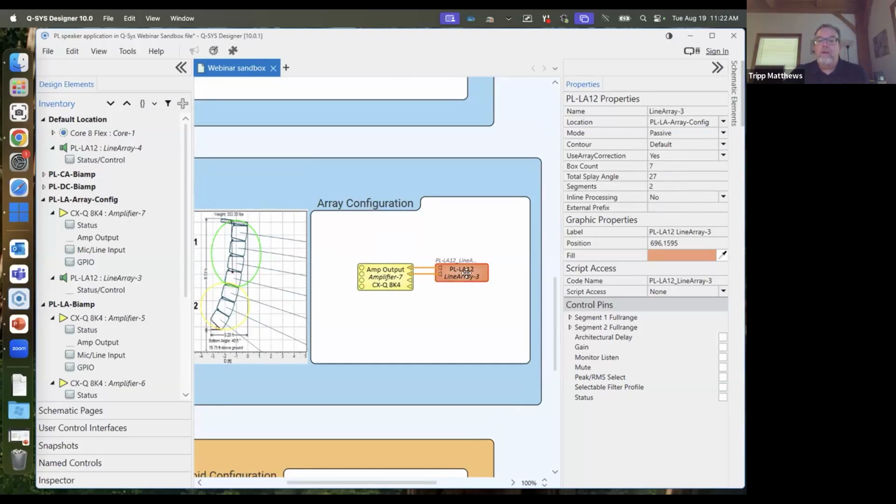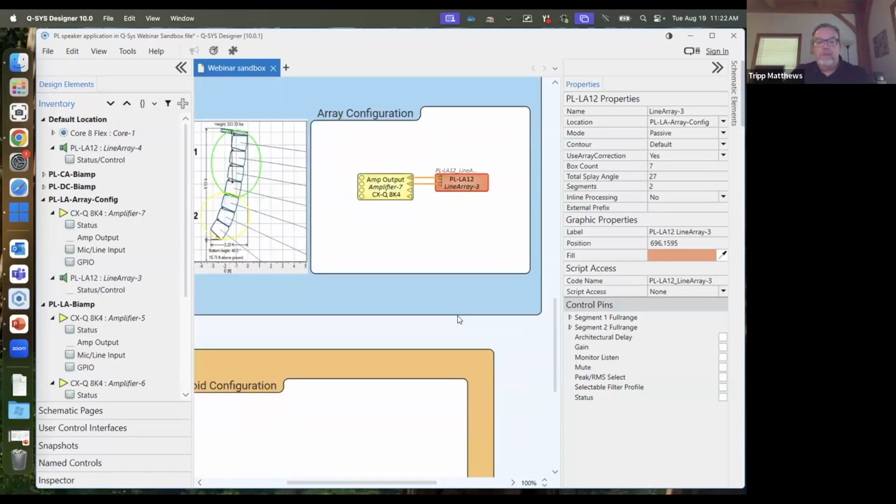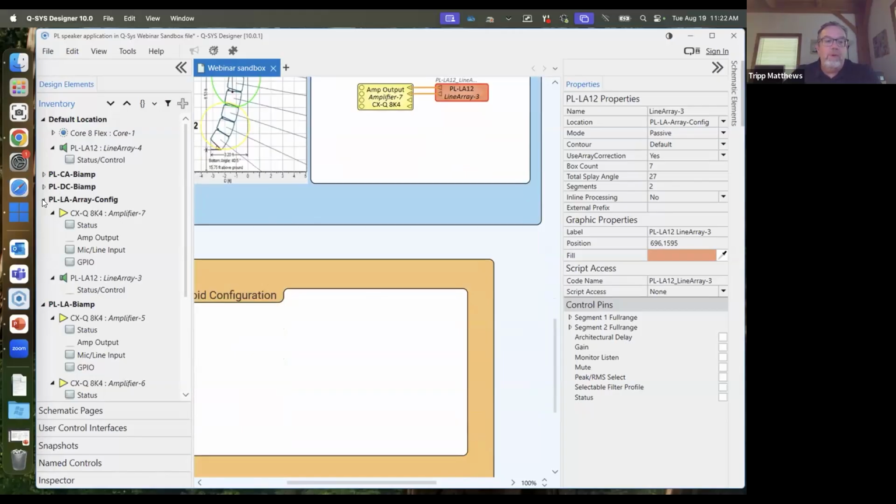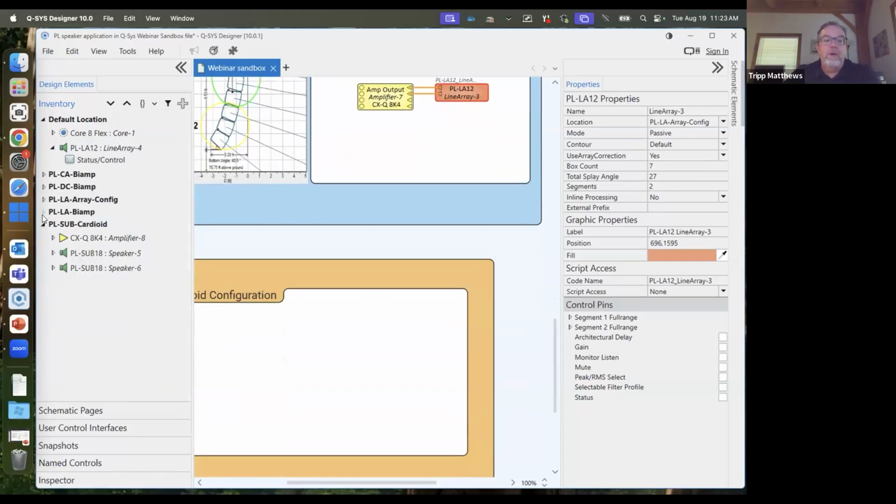But we are now creating a very smooth output between high and low frequency. If it was done with the 2 connectors, you're going to have some really inappropriate sound and things that you feel like you got to go and do a lot of EQ with to balance out when you don't need to, because we're automatically doing that for you with our array correction, and that's how we know how to do it. So I hope that helps a lot down the road when you do deploy some of these boxes, that you will start at a good spot. And I'm going to hop back over here